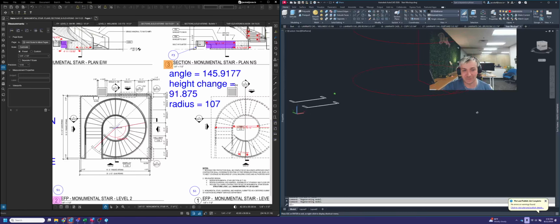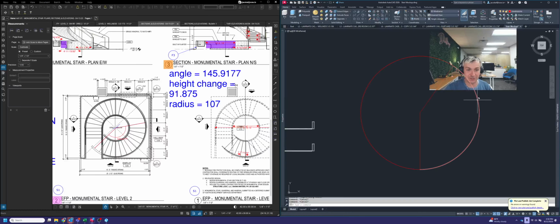Okay, so really then from there, all you need to do when you go to do the sweep, now that you've got the math part down and the helix part drawn, if you want to check it, you can go top down and you shouldn't see any sort of deflection between the helix and the circle. Of course now it's doing it because I'm zoomed in, I think, but it should be pretty spot on.